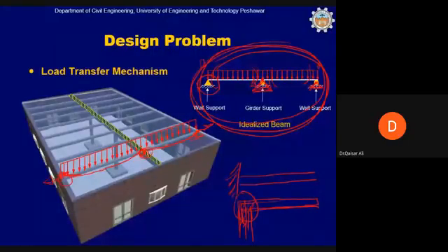So hinge support will offer resistance to this thermal movement. However, from a practical point of view, we know that whenever there is a thermal movement, it cannot be completely resisted by the walls, especially when the beam is supported on the walls and only friction between the beam and the wall is responsible for resisting this thermal movement. So this will not be possible. For this reason, we will provide one support as hinge support and the other as roller support, so that this support can move.